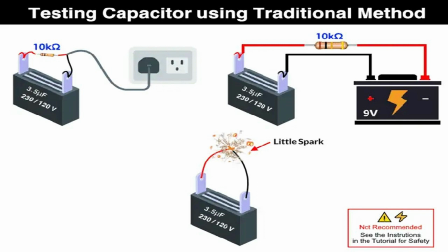Note, keep in mind that a polar capacitor should not be connected to the AC supply. On the other hand, a nonpolar capacitor can be attached to the DC supply because they are back-to-back electrolytic capacitors. As we know that capacitors block DC but let pass the AC, but still it will charge with the DC supply source until it reaches the terminal voltage level. In short, nonpolar capacitors can be operated on both AC and DC supplies, while polar capacitors only operate on DC.